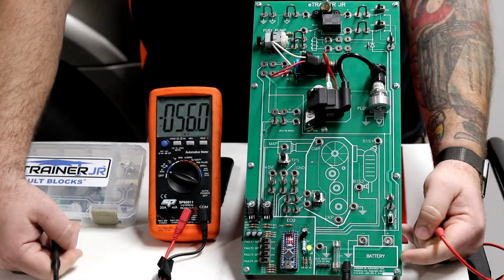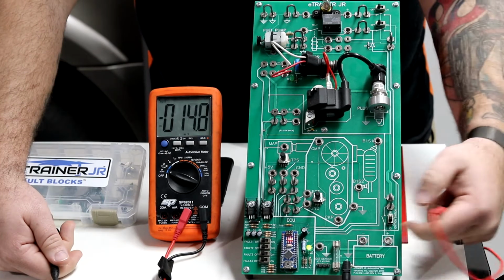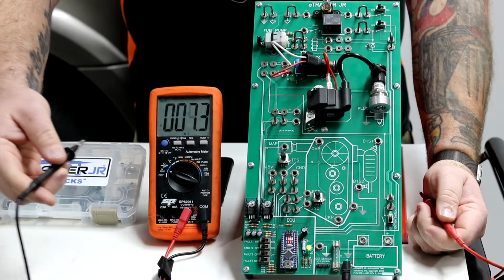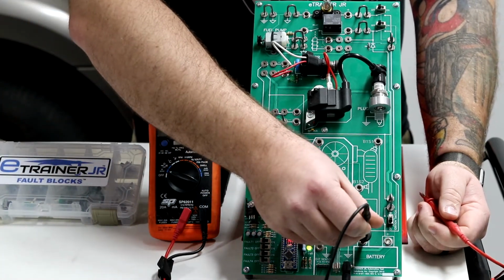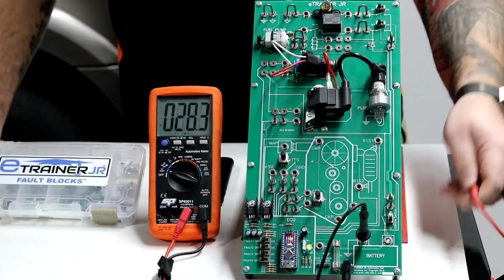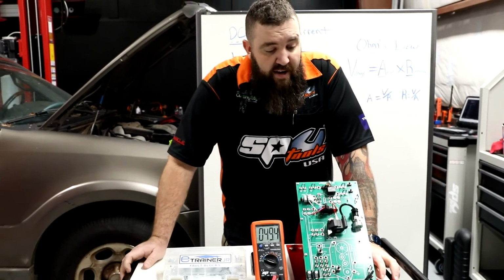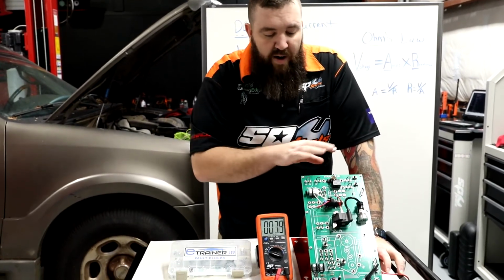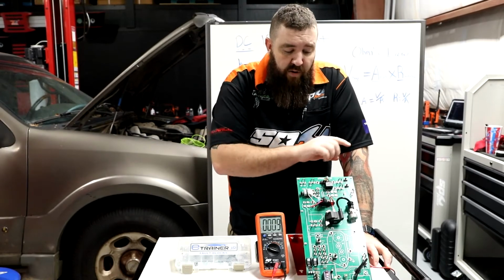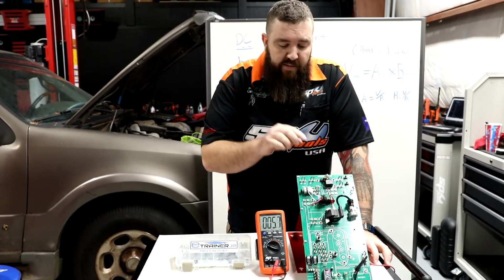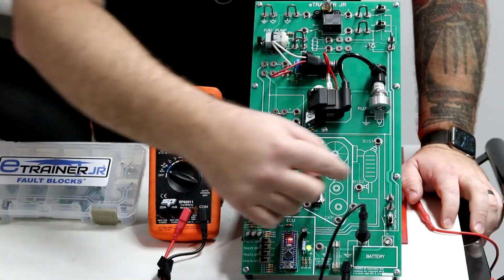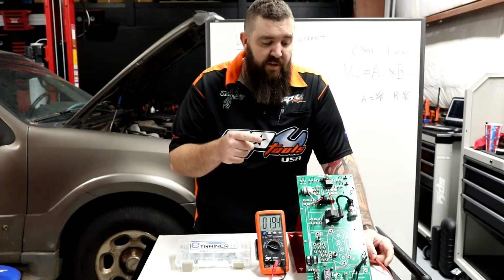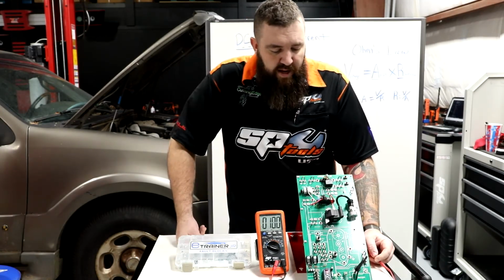So as you guys can see on our little test platform, we have our battery here in the lower right hand corner. And what we're going to be doing for nominal testing is we're going to have our negative lead on the negative post of the battery, because that is the overall end flow of the current in the circuit. After the electricity flows through whatever items or whatever modules or lights, it's going to go to a chassis ground, which will eventually go back up to the negative post of the battery for the negative return. So for our voltage sector, we're going to leave that one there on the negative post.